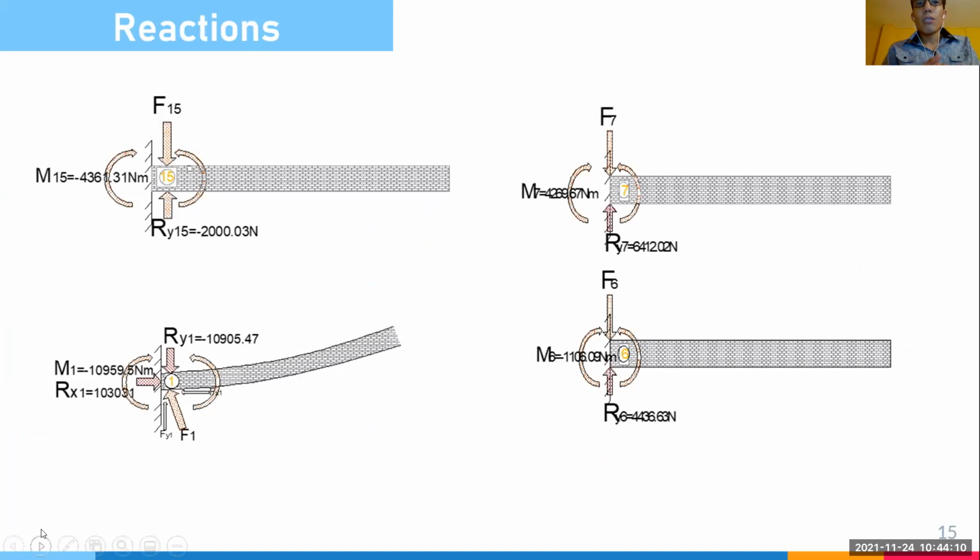The code gives us the total value of the force and moment acting in every joint, in which the forces and moments calculated in an analytical way must be subtracted to obtain the reactions and external moments at the clamped elements.